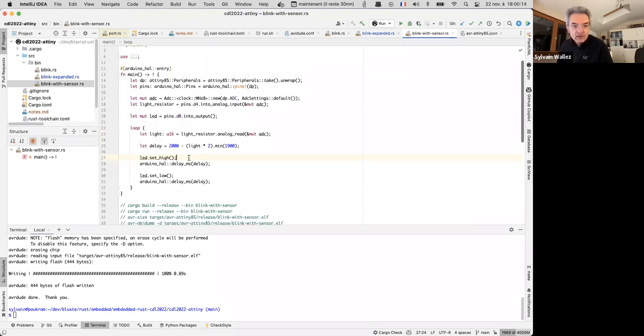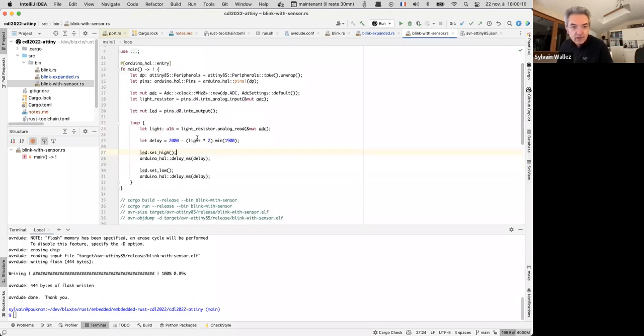Yeah, so you see here that I limit the sensor value to a maximum value because I made the mistake of not limiting it, and I went above the number. I had an integer underflow error, and then suddenly it started to wait for 1 minute.